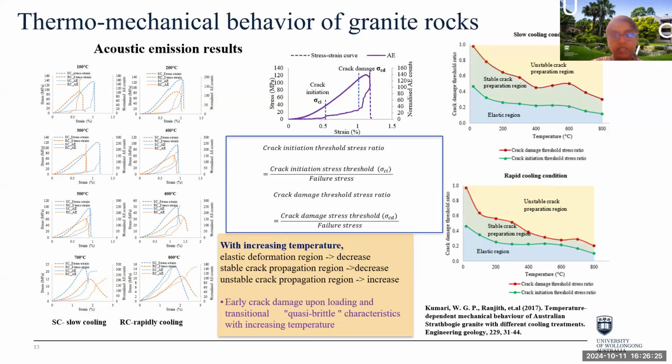Researchers have divided crack formation into different stages. For example, crack closure, crack initiation, secondary cracking, crack damage, etc. Considering the experimental observations of cumulative acoustic energy plots, here we identified 3 different stages.